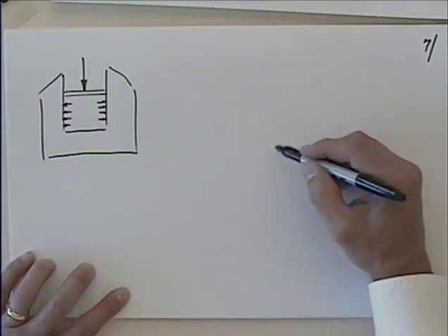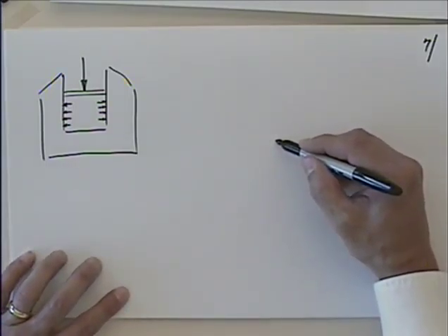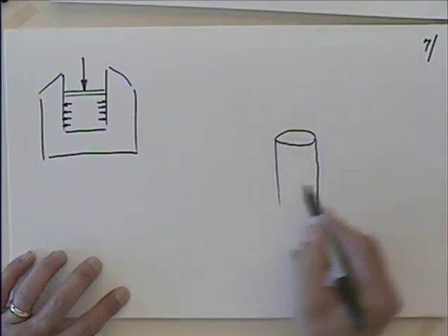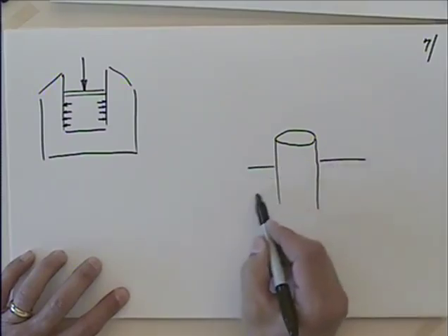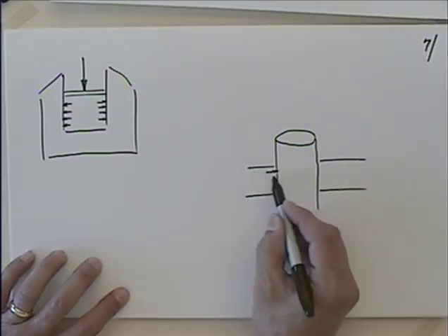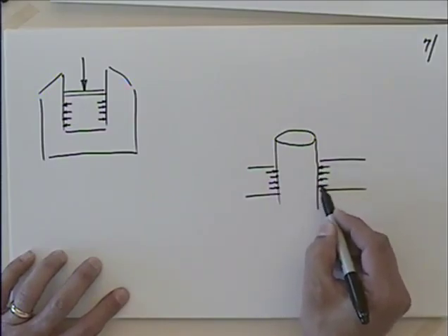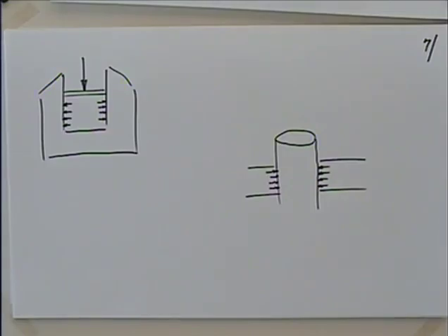We're not necessarily going to look at an example like this, but what happens when you have some sort of a press fit? So you take this shaft and you have something that is pressed on it. Is there pressure that's developed here? Yeah, absolutely. And that has to do with the amount of the press fit and the relative stiffness of the two materials. So we'll look at situations like that and talk about those, and believe it or not, those are going to relate to Hooke's law. And then we'll look at how Hooke's law will transform us into talking about Mohr's circle of strain. So that's where we'll go next time.